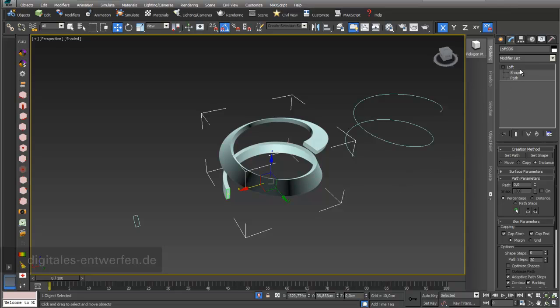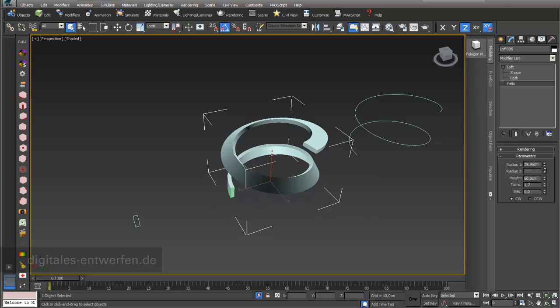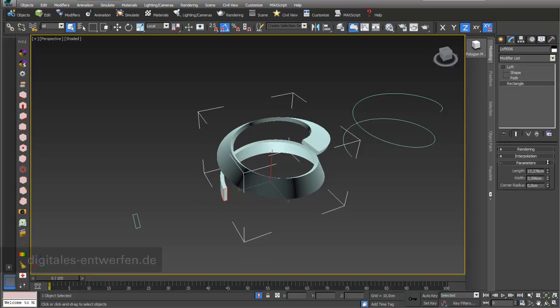You can also do it differently. You can also go into my loft substructure. I choose path, and then you're also in your helix, and here you can do the same. You can see that they're both turning and rotating. It really depends on what you do. And also in terms of my path, I have to select my little triangle here, and then you can see here's my triangle, and I can still change this shape, this section.